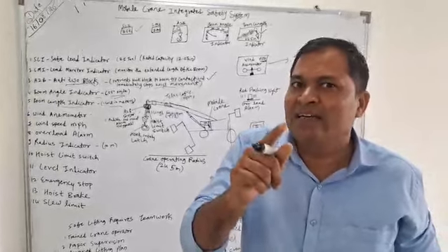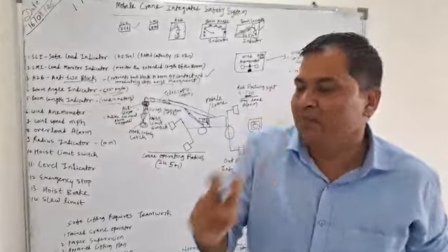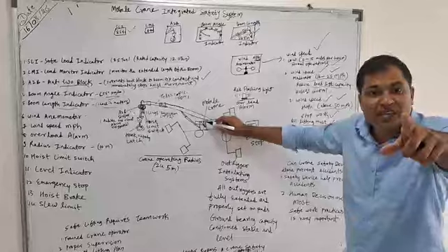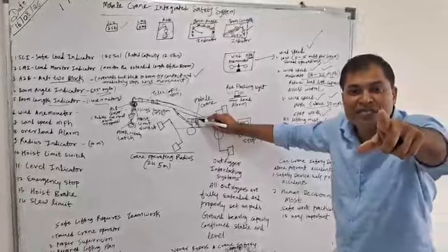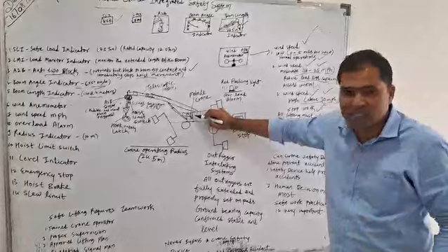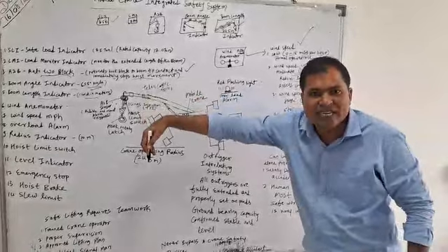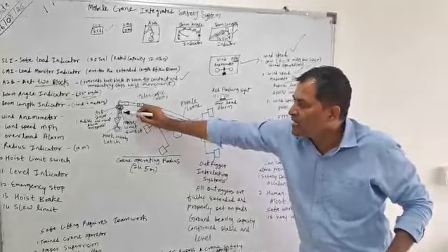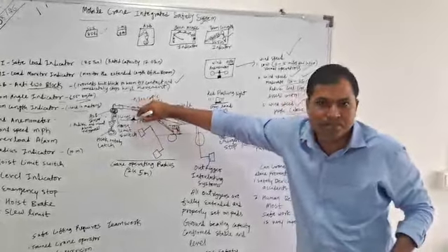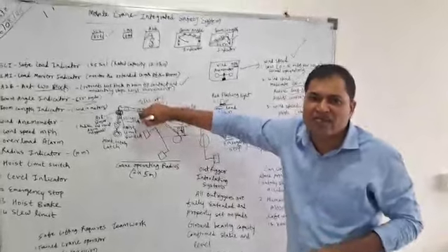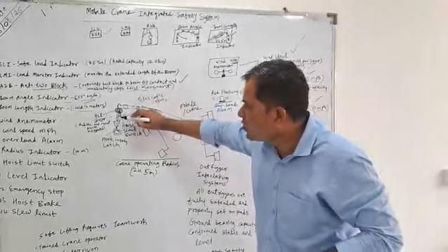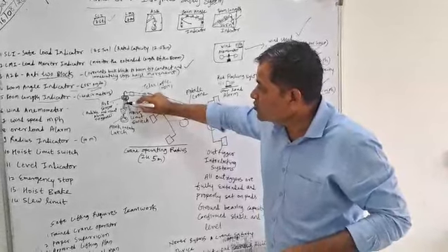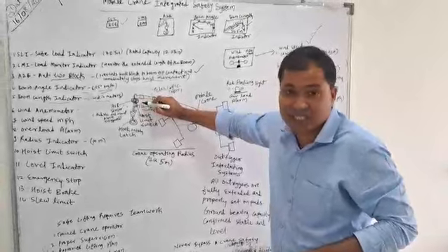Red flashing light, if you get the alarm related to the red flashing light, it means that something went wrong. You have to immediately stop your work, check all the things, check the load lifting capacity, what amount of load is fixed over here. Okay, check the capacity of the slings as well. Why? Because if you want to lift a load of around 9 to 10 ton, you must know the load lifting capacity of these slings as well.